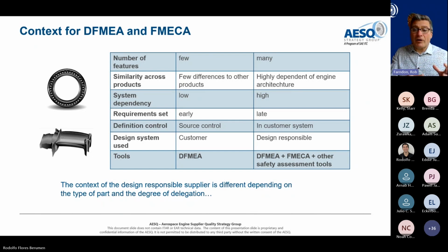When you're earlier on in the design process and trying to evaluate your concept at the component level for potential failure modes, that is where doing a DFMEA and trying to dream up what can go wrong yields benefit. A FMECA doesn't sit in that space. It sits in higher complexity and looking at a big system.